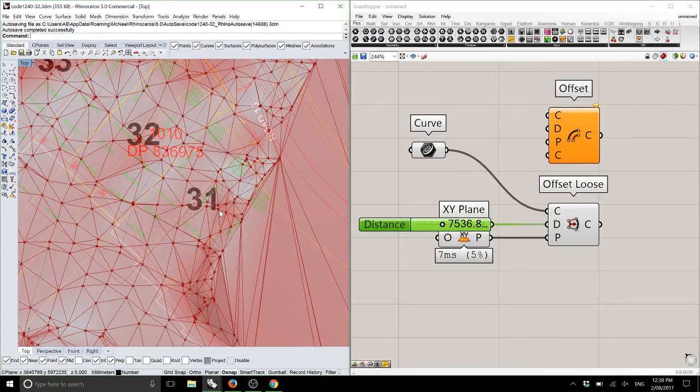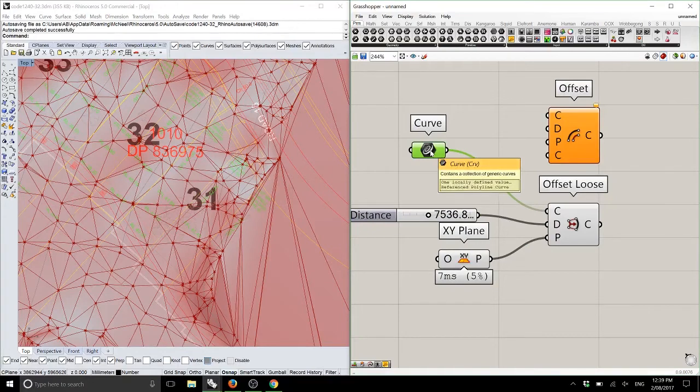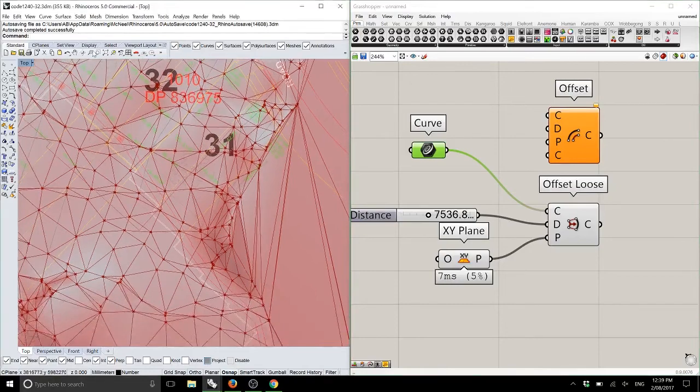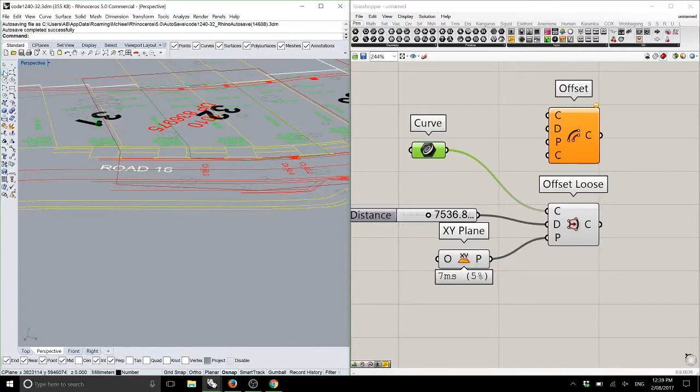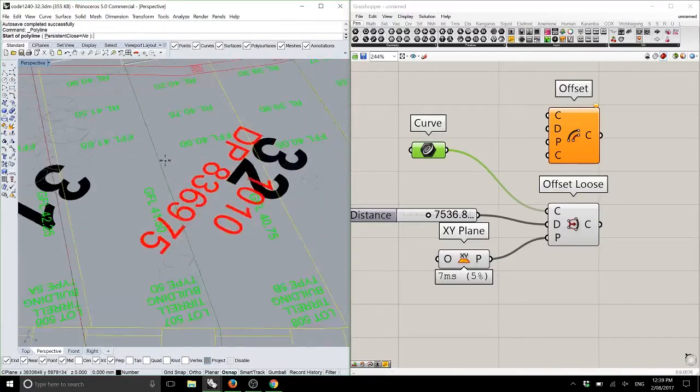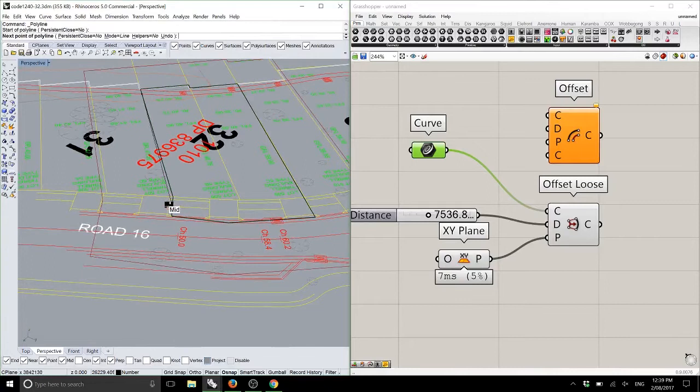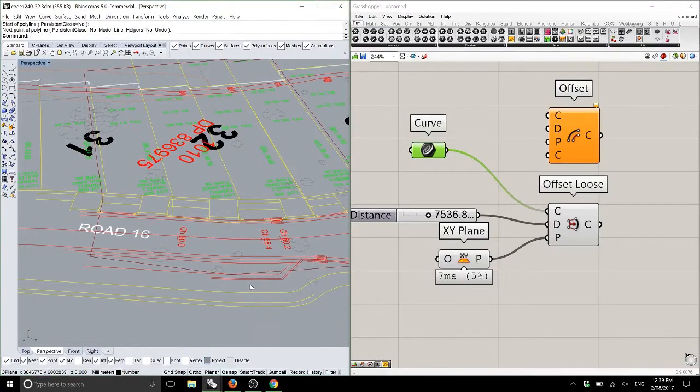First start, the curve. Which curve do you select? I drew one. Where did you do it? I drew it around the boundary. No, that's like the second or third step. The first one, the curve. This one? Yeah. I literally went into the Rhino model and I drew the curve, using the Polyline tool. I went to my site and I drew that boundary there.